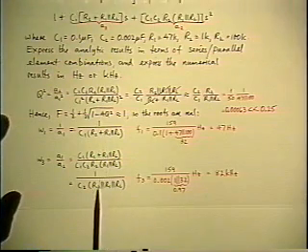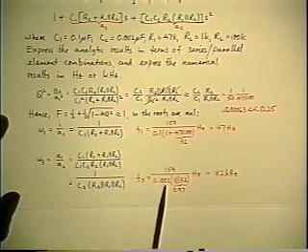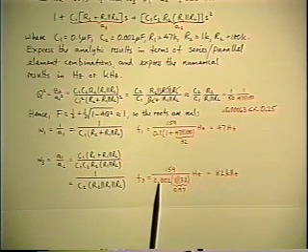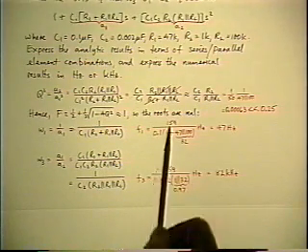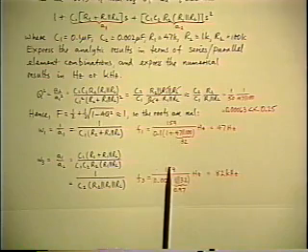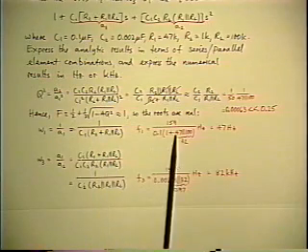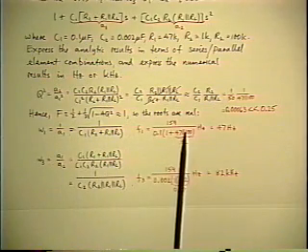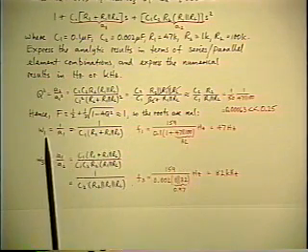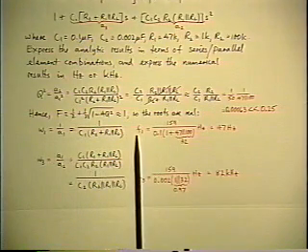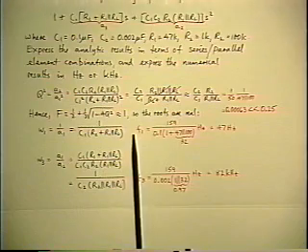So these are the two analytic results now, and here's the substitution of numerical values. Another little trick that I'm sure you've all discovered long ago. When you change from symbols to numbers to do with frequencies, the formulas give frequencies in radians per second, and the numbers you want to come out in hertz, and there's a 2 pi in between.